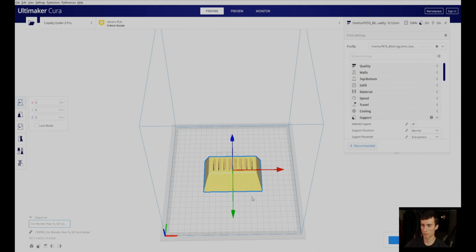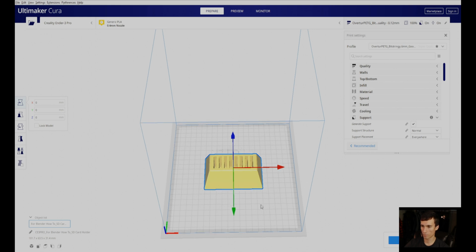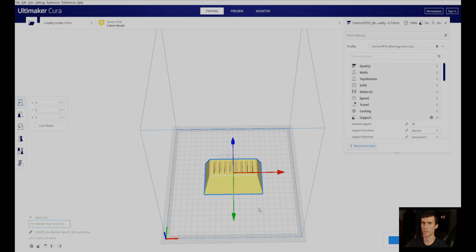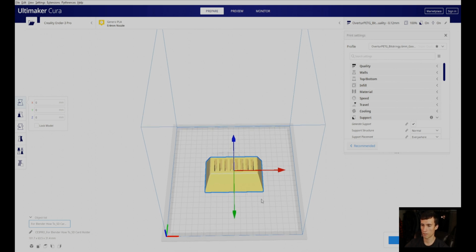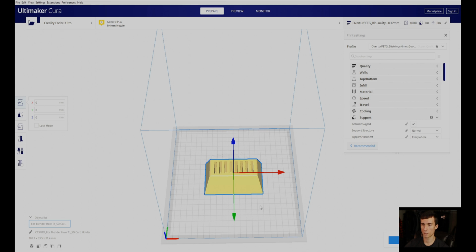I'm not going to go over it, but basically you can create a plane and make that plane what cuts your part in half, or make a plane that's not fully 2D but slightly 3D, but very small, so it doesn't really affect the geometry of your model. That's what I do to cut things. Then you can position the cut nicely.